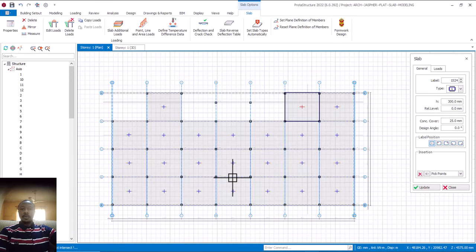That means the column you are using from the beginning is the one that is going to the last floor, because you cannot start changing your column position, knowing fully well that slabs are not meant to carry columns. What is meant to carry columns is beams, and since in this case there is no beam, automatically your column from the ground floor must go from start to finish, to the end of the structure. Are we together now?